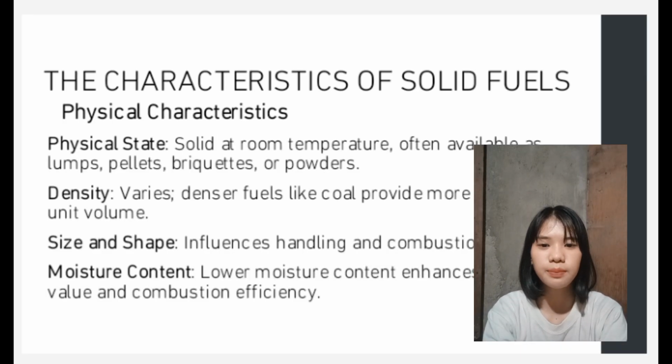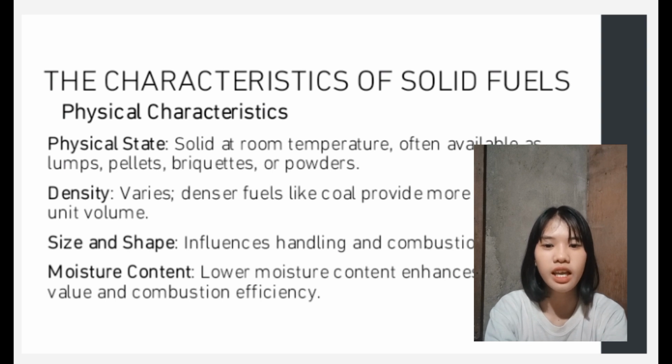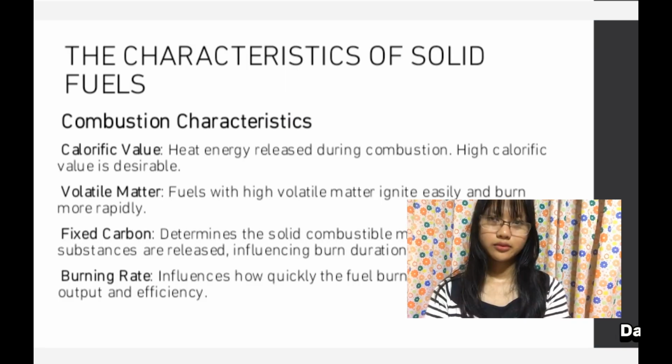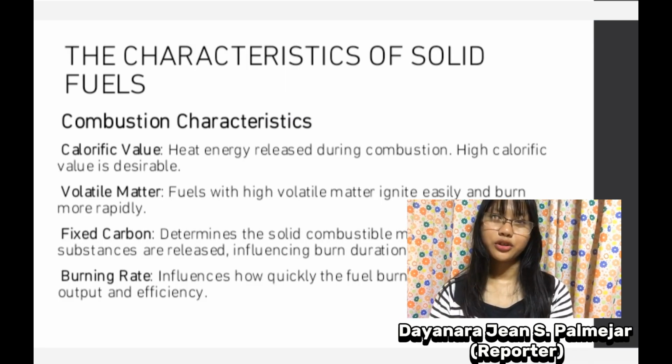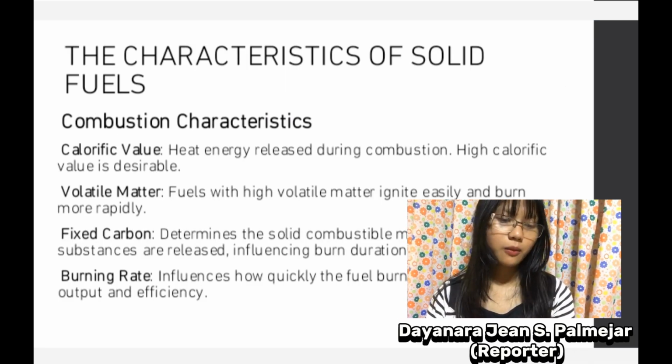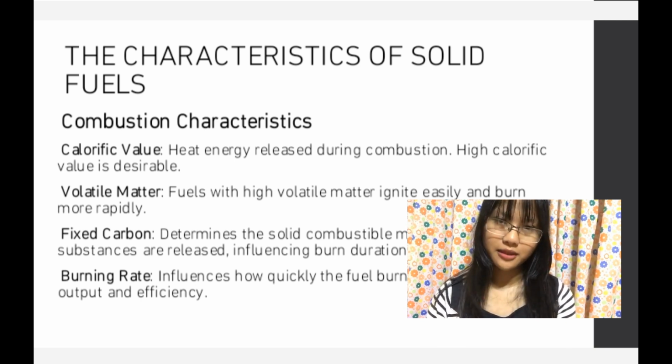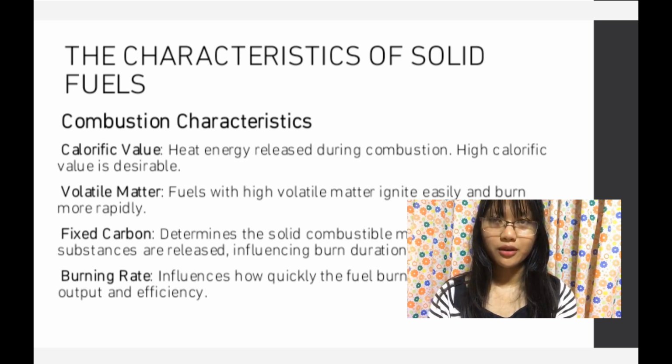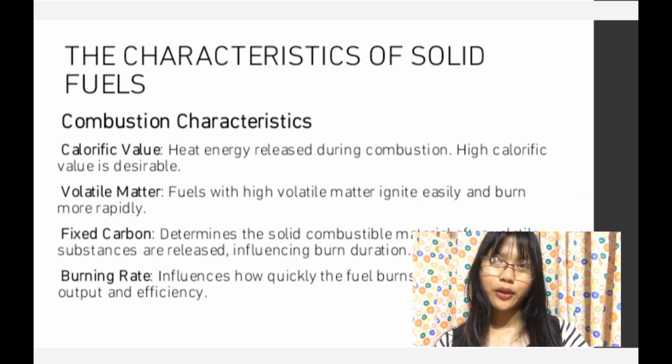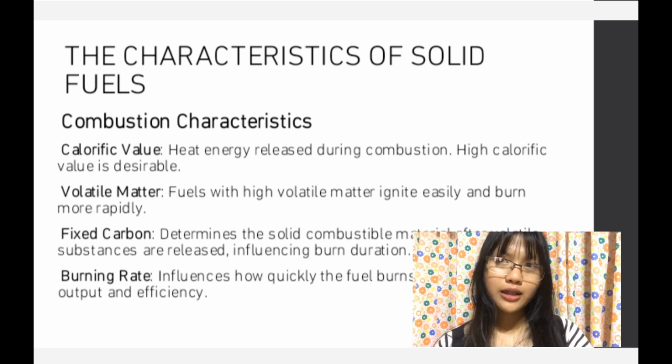They also have physical characteristics, which are physical state, density, size and shape, and moisture content. So what is combustion characteristic? Combustion characteristic refers to the properties and behavior of a substance during its combustion process. Core examples of combustion characteristics are calorific value, volatile matter, fixed carbon, and burning rate.